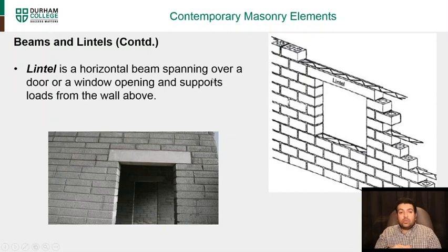A lintel is a horizontal beam spanning over a door or window opening, and it supports the load from the wall above. It can be either a solid beam, or you could have masonry units with reinforcement, but for a window or door opening it's usually a solid beam.